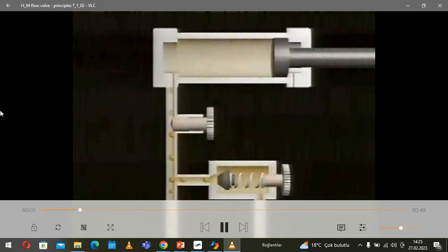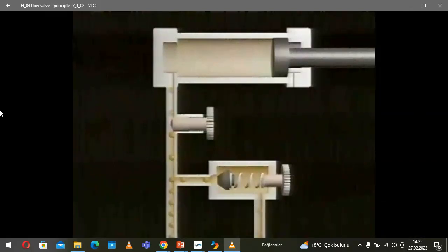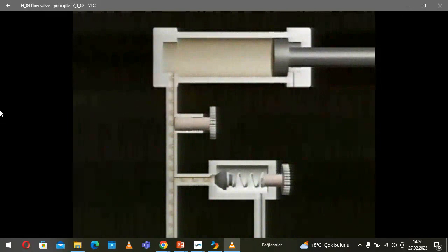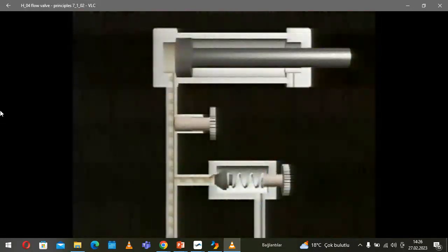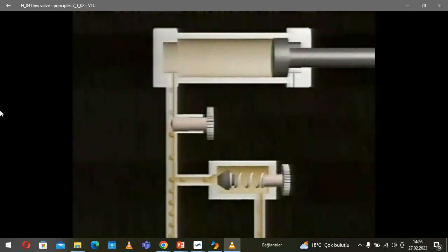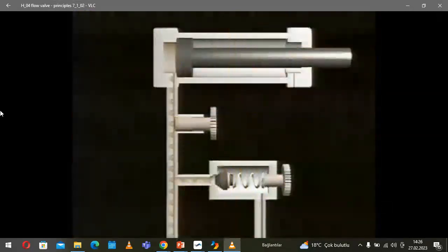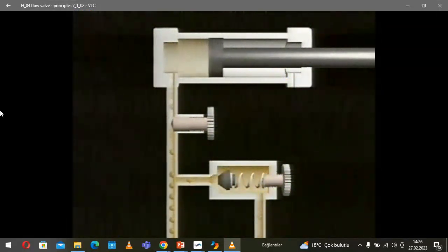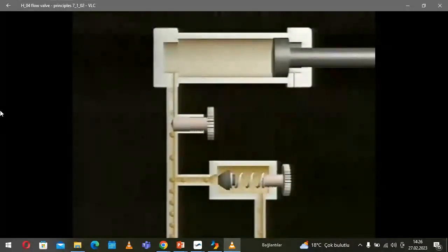Here we see first the working speed of the cylinder when the restrictor is open. If the restrictor narrows the passage through the line, pressure rises upstream of the point of restriction. This causes the pressure relief valve to begin to open and the flow rate is divided. One part of it flows to the cylinder, the other back to the tank. So flow rate is reduced by the interaction of two valves. Using the restrictor increases pressure by opening the pressure relief valve and channeling part of the flow rate back to the tank.